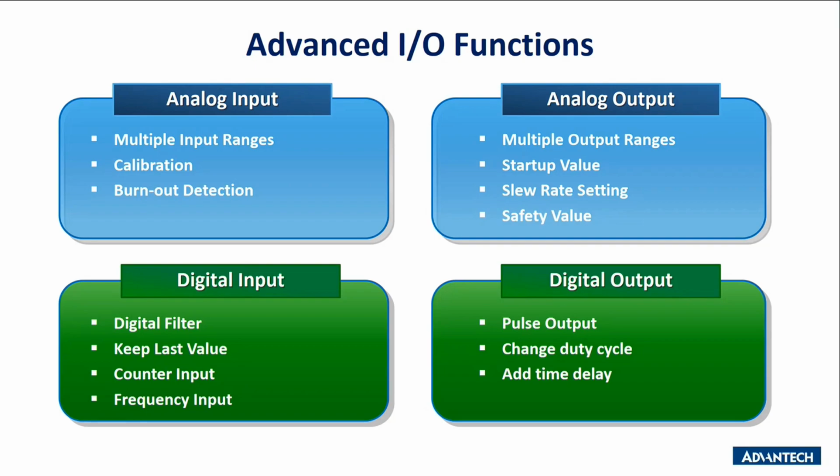And also the counter function will be handled by the I/O module itself. When the I/O module is powered off, there's this function of keeping the last value, and the data won't be erased completely. In some site implementations, when there's some environmental noise or vibration, this digital filter plays an important role as it can eliminate such external factors.